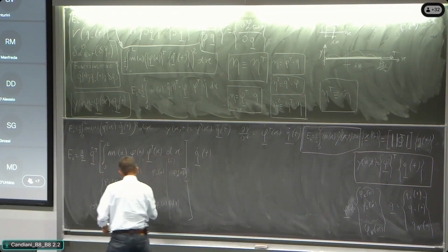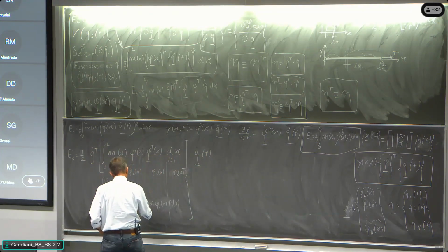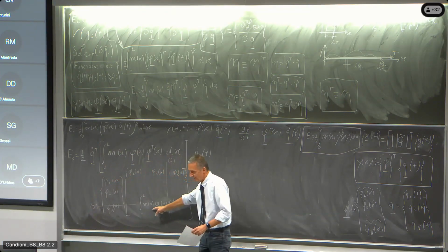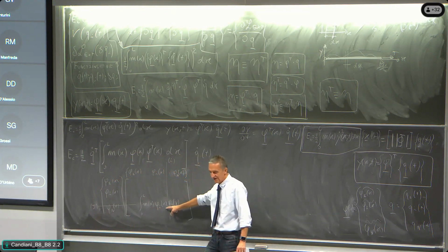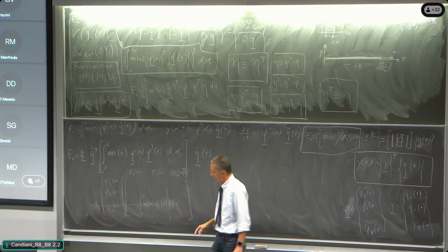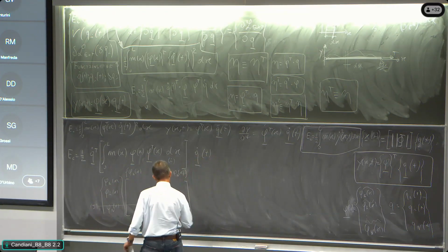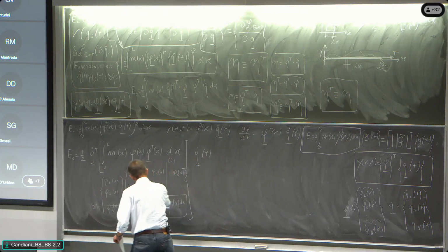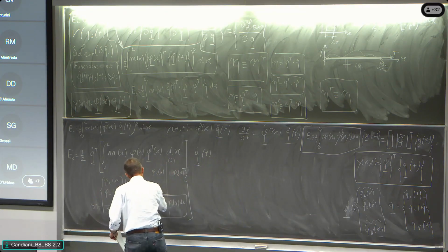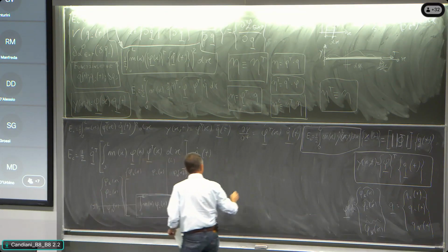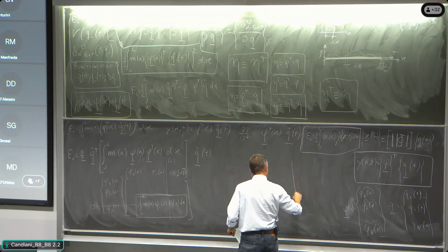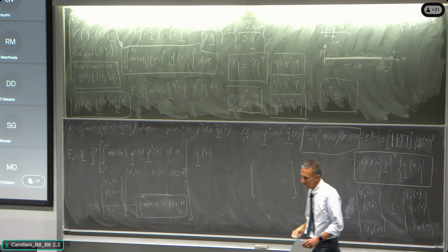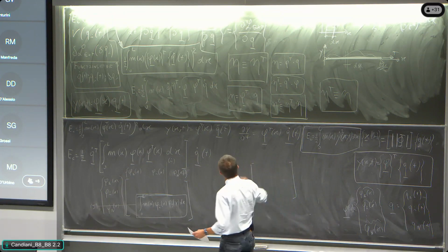And so what we are writing is that in the ij location, we have integral 0L, distribution of mass, eigenfunction phi I, eigenfunction phi j, multiplied dx. And this is finished. And what are we finding? We are finding that at the location ij of the product phi transposed m phi in the n degree of freedom, okay?